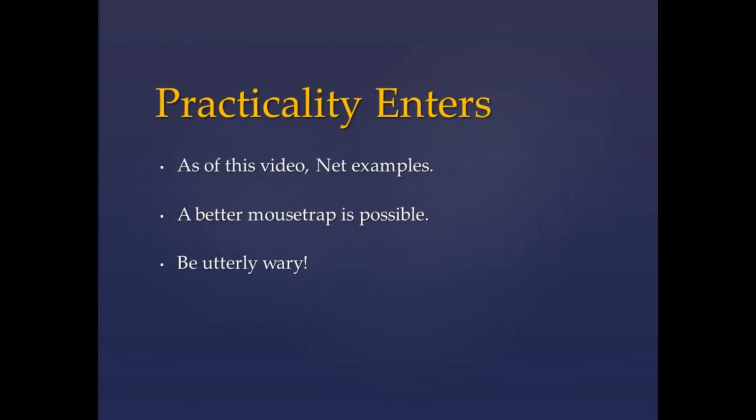You can find video that duplicates my experiences in industry in which even those who are forced to do ternary analysis cobble together a coarse diagram like this for the UFL, LFL, and MinO2 data, and then struggle through estimates of various properties and must then add a generous safety factor to any determinations they make.